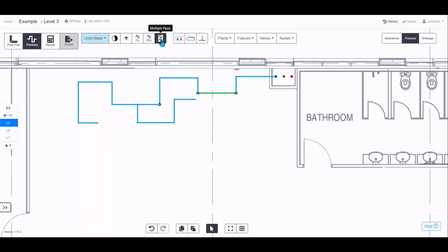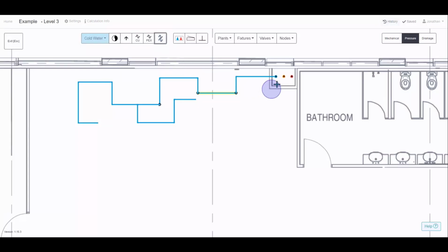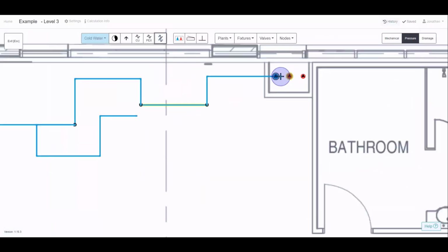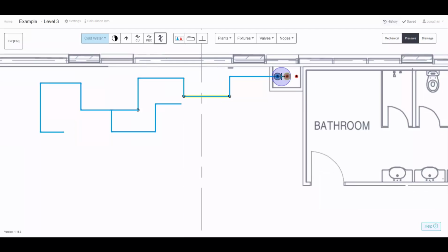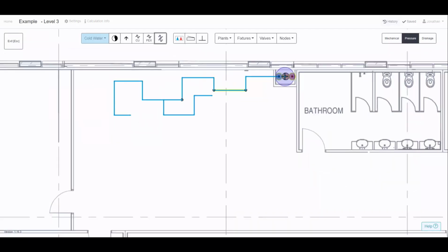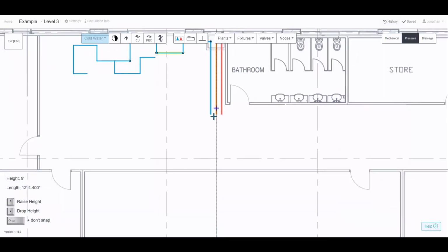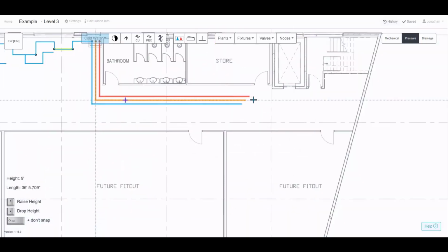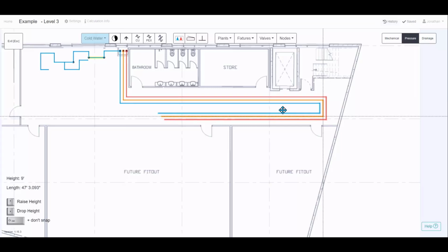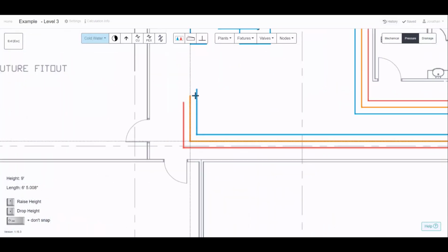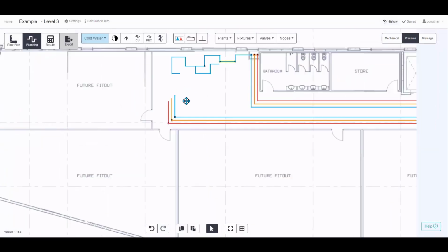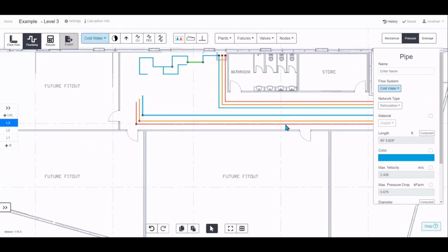And then the last one I'll show here is the multi-pipes. So the way this works is whatever is highlighted in this circle, so here there will be 2 pipes, here it's 3 pipes. You can now start, if all your pipes are following the same route, start clicking that around. And once again, in the bottom left, you can control the height if you want to. And those pipes can be individually moved, deleted, or whatever needs to happen.